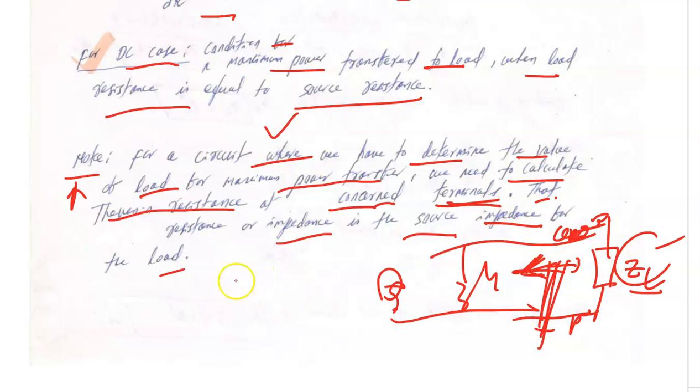As usual we have done, for example, you first find the Thevenin resistance. Let's say I got the Thevenin resistance as this. So maximum power transfer will be, if ZL is resistive, use the special case. If ZL has both reactance and resistance, but only resistance can be varied, you use case 3. And if both resistance and reactance of ZL can be varied, use case 1. As simple.